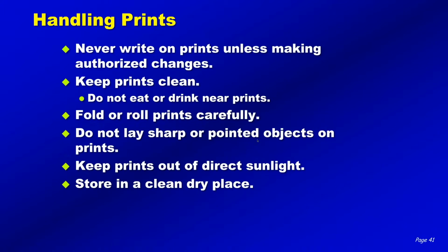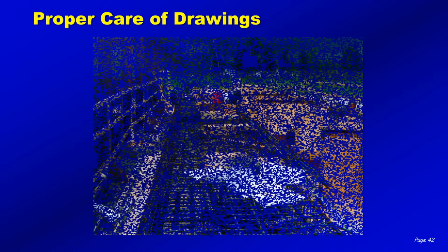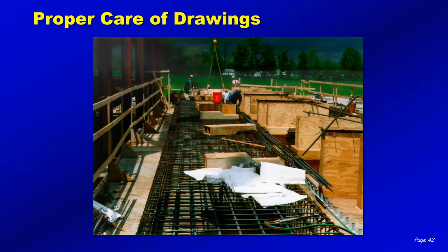An important thing about handling prints, never write on the prints unless you're making authorized changes. Keep prints clean. Don't eat or drink over the top of them. Some people don't seem to realize that. Don't fold them. Roll the prints up carefully. You fold them, it makes some creases in them. If you fold and unfold, fold and unfold, it gets to be a problem. Don't lay sharp objects on them. Don't leave them out in direct sunshine. And store them in a nice, clean, dry place. Like these people here. They just love their drawings.